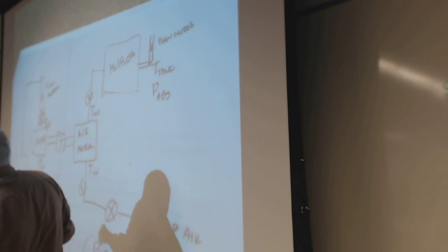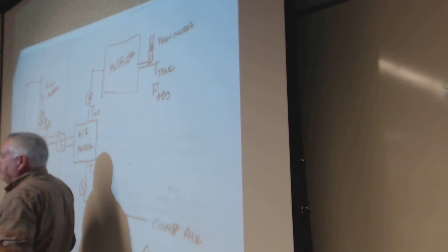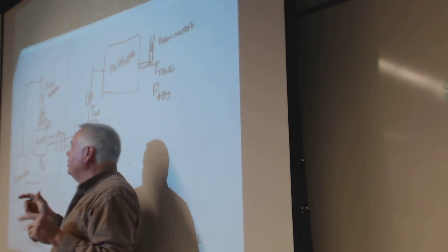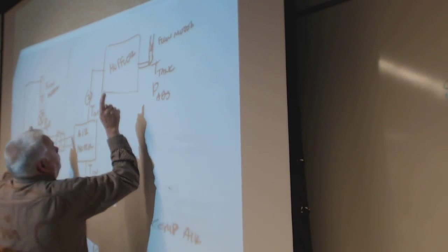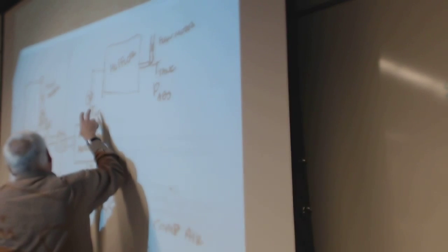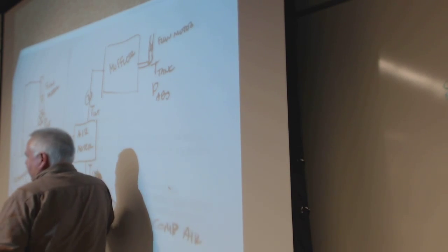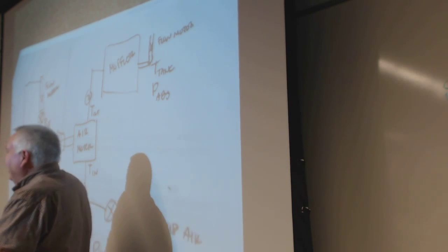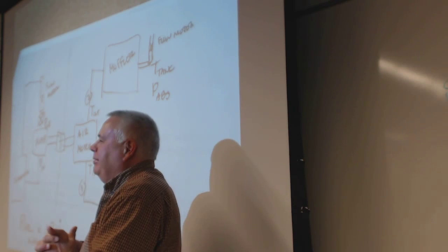Yes, basically. And that's one of the tricks. You probably want to set up so that one person takes the data, somebody's reading the flow meters, and somebody's reading the temperatures or pressures. Too big a group doesn't help. We're talking probably 3 or 4 people.